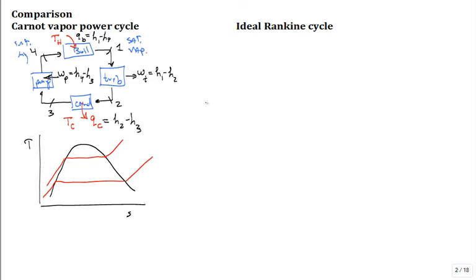All right. Then we can sketch this cycle on a diagram just to get familiar. On a temperature entropy diagram, put the dome, put a line of high pressure, put a line of low pressure, and state 1, saturated vapor. State 2, isentropic expansion. So it's constant S from high pressure to low pressure. State 3, we stop it such that when we put it through this very special pump, we're back to state 4, which is saturated liquid.